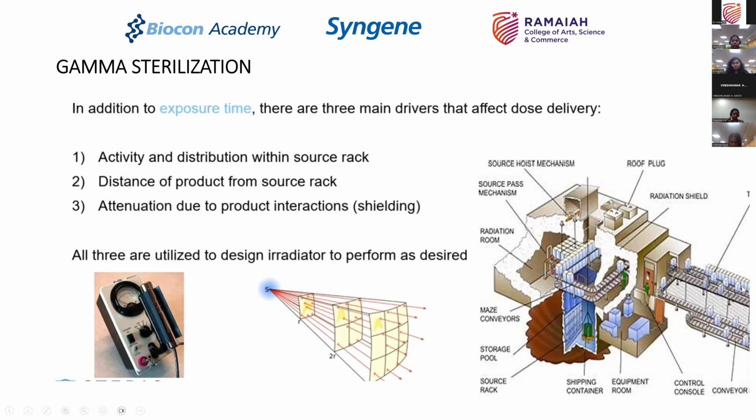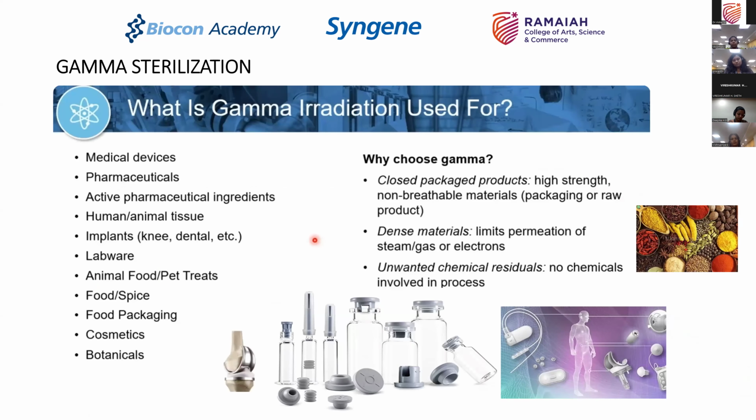When you get a material out, there are portable devices like this one on the left hand side that I'm showing you, which are used to measure if a particular container which has come out of gamma irradiation has radiation in excess of what is permissible. Okay, so these are the in-process controls which are definitely there in a tunnel of a gamma sterilization. What is it used for?